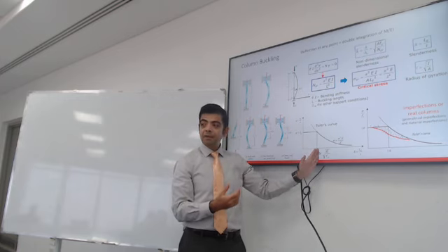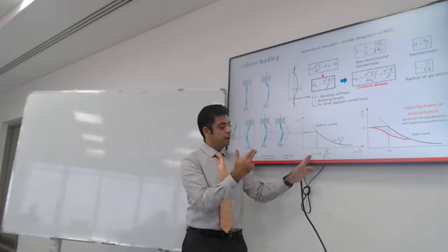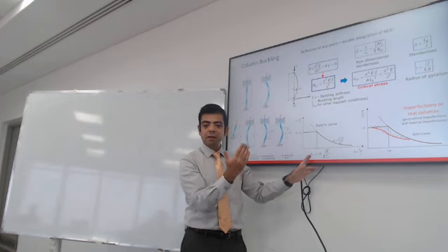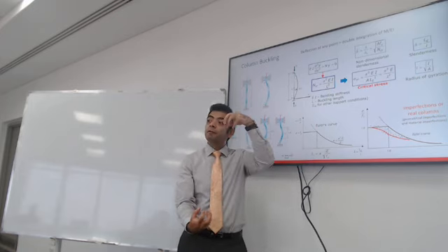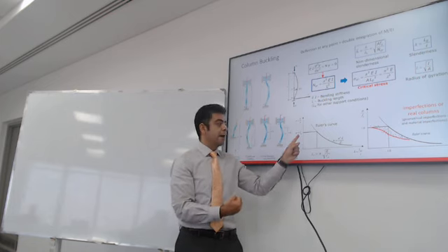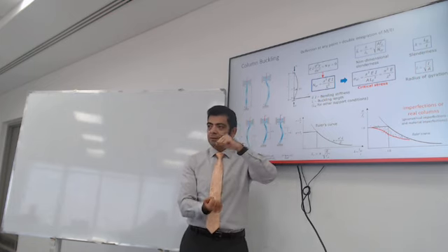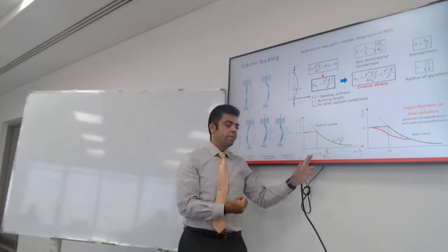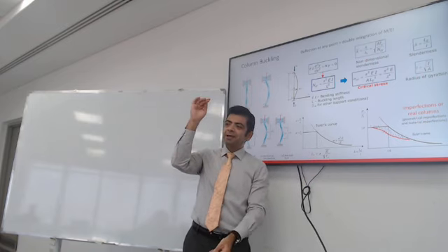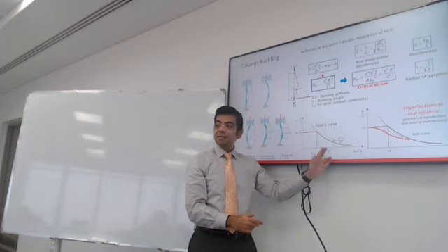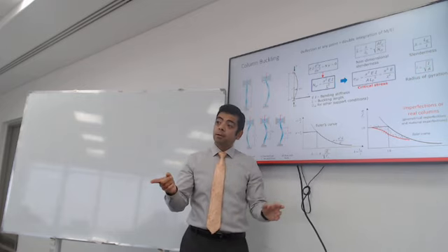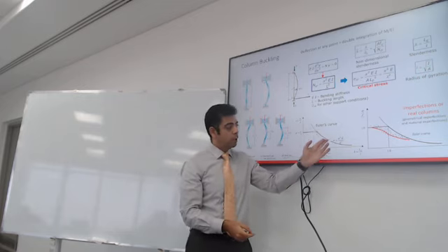At this line, if your slenderness ratio is smaller than that, the column is probably short and stiff, and it will fail under yield compressive stress. If you calculate your length of the column divided by the geometry, and it's bigger than this line, now your column will buckle. And it will buckle according to this curve.